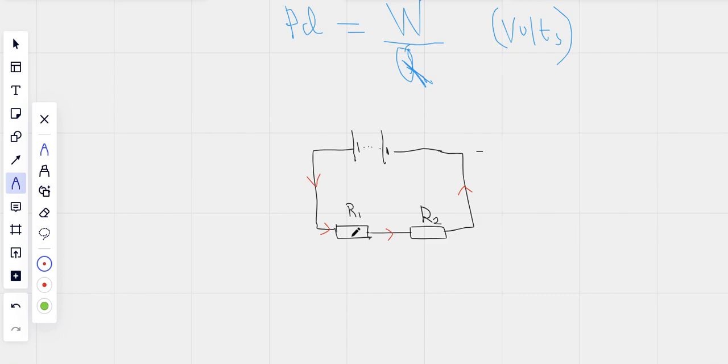So if you want to find the voltage in R1, we have to connect a voltmeter parallel to R1. If I want a singular voltage here, I have to connect a voltmeter across R1 to find my V1. So I can find the first voltage called V1. These are terminals. You see, I always put a point before I connect. That's where you terminate the wire. So the voltage is different in the different components.